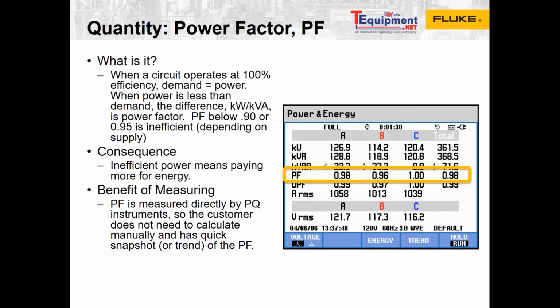And to do this, they install things like power factor correction equipment. This monitors the power factor and automatically switches in compensation in line with the electrical circuit. And then to choose the right equipment, Fluke's power quality analyzers actually measure the consumed power and log the power factor. So you can decide on which equipment to install.